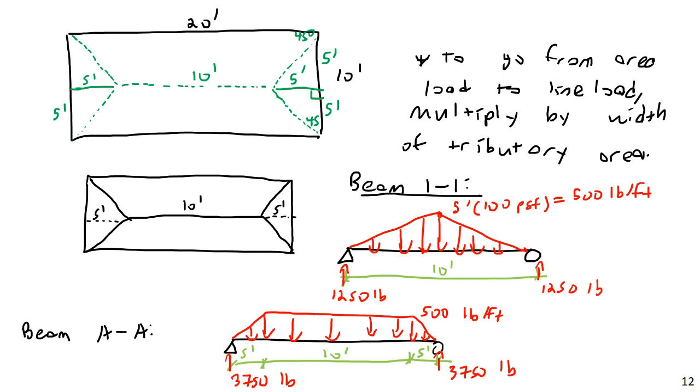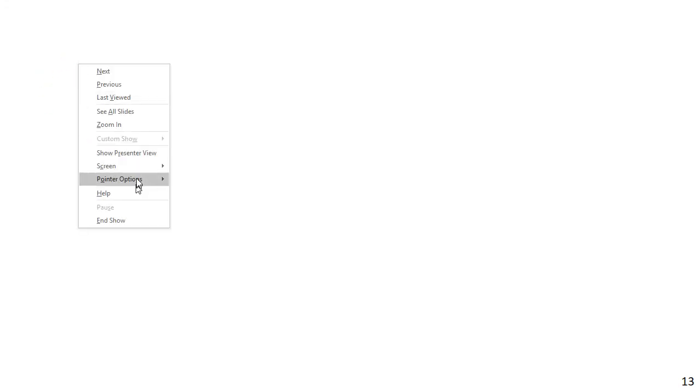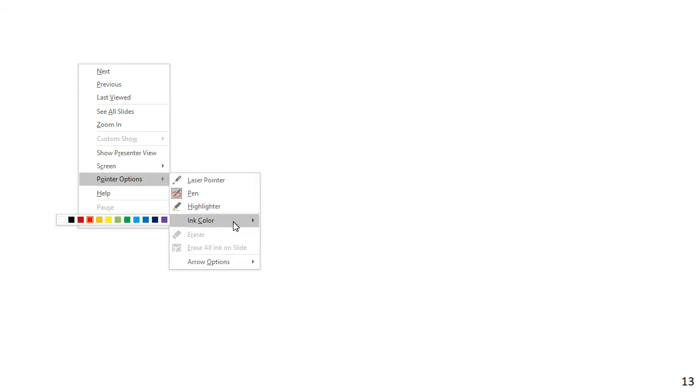Okay. Next, I'd like to look at the process of load path for lateral loads, and in particular, the example of wind loading. For seismic, it's a bit more complex, and I don't necessarily want to work through a load path for that one. It's more complex because of the nature of inertia, seismic inertia, and how loads distribute through structures that way. But for wind, it's a lot easier to understand.